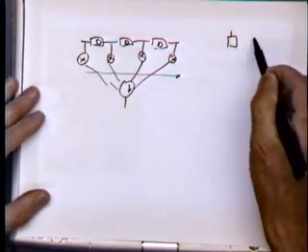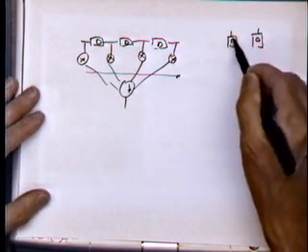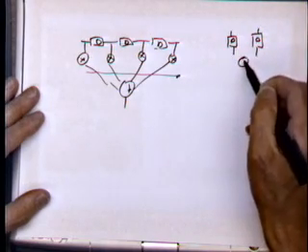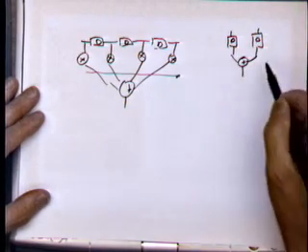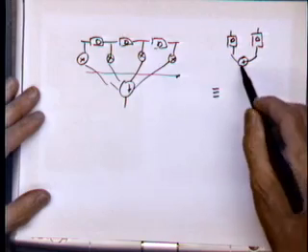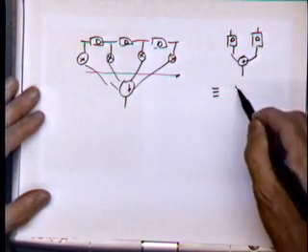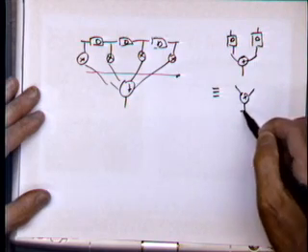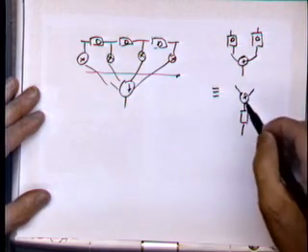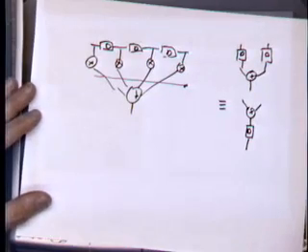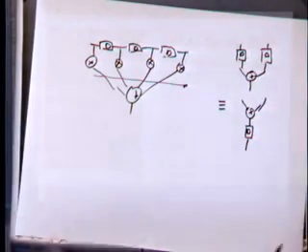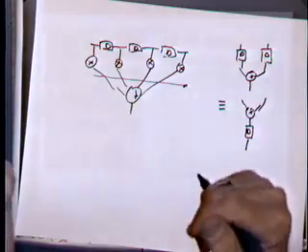If I have a delay and then, let's say, an add or a multiply, whatever it is, this is completely equivalent to having the delays move over the add: take the add first, add the two numbers together, and then put the delay at the output. There's no difference between the two. So I can use this to move delays around and change the critical path.